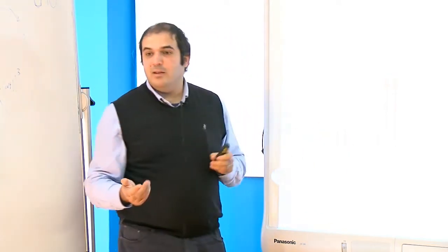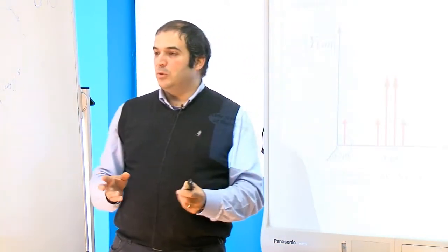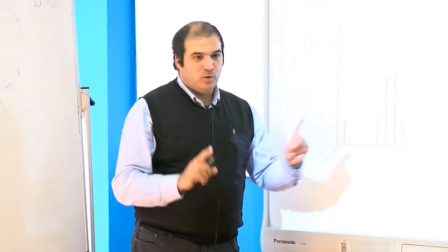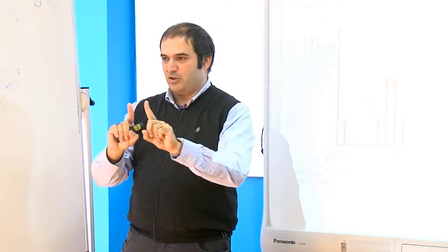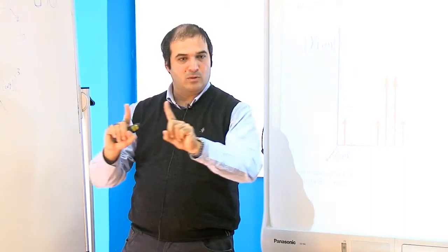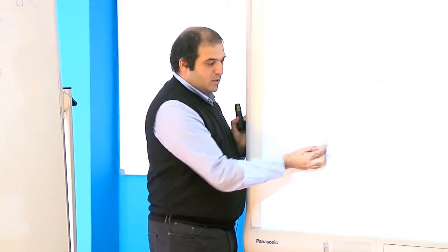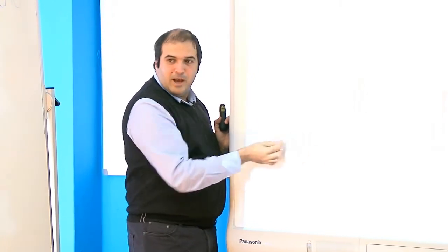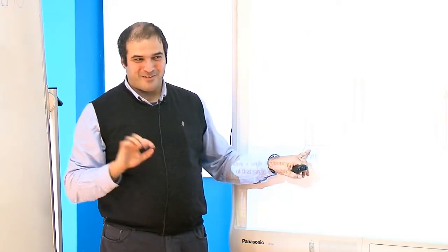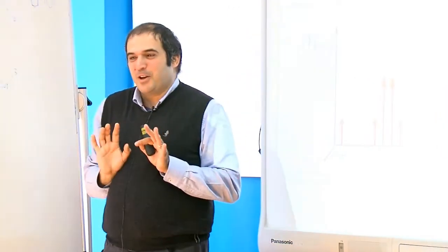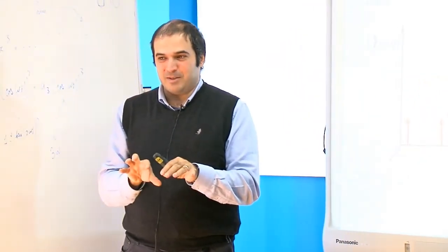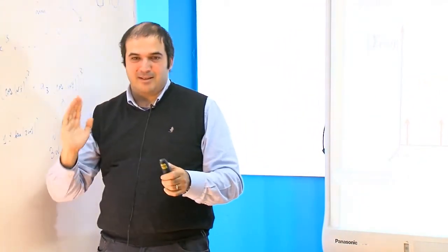So one thing they do when they want to do memory effects, they pick up the two tones and they do this. They change the separation between the tones. And then when you do this, if you look at the spectrum, what you are going to see, this will go up and down. But again, they are expecting that superposition will work at video bandwidth, because you are not exciting everything at the same time. You are exciting one and another and so on.